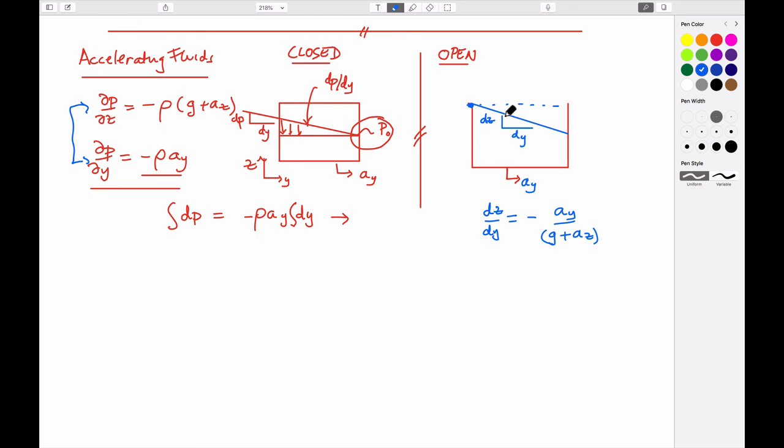And so this gives you the inclination of this surface here, and this surface is actually the same inclination as the isobars that would develop in this, which actually are the same as the inclination of the isobars that you'd have in this system. They're directly analogous because the acceleration that you're driving in this case is given by this, and in this case the free surface is what gives you this distribution of pressures.